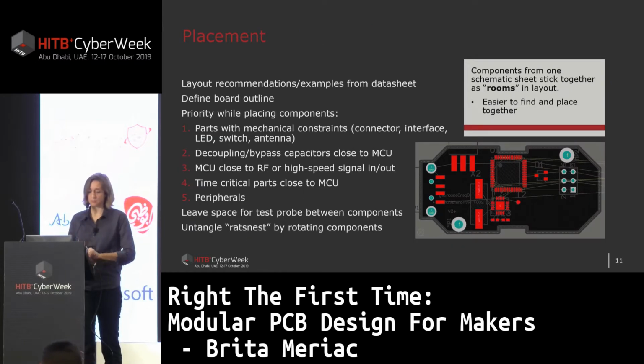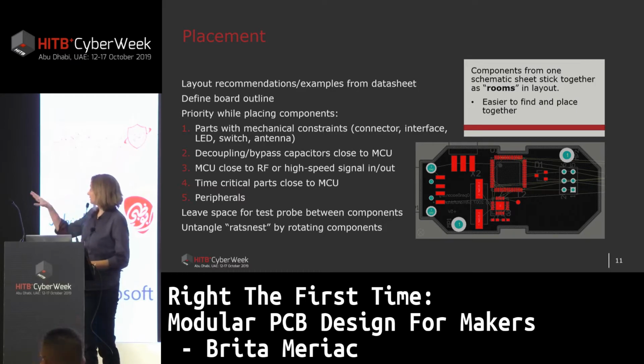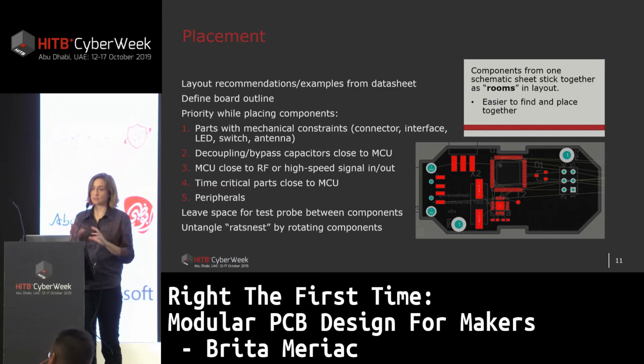So one more thing is to be done before starting the layout. It's defining your board shape, and then you can import all the components into your layout view. I didn't say anything about the layout software, so I would recommend KiCad for private purposes and Altium for professional use, but there are many more out there. So when you import your components in your layout view, you have huge entanglements of all the nets and the buses connecting pins. But this soon untangles once you start rotating the components so the right pins face each other.